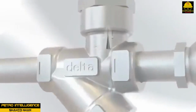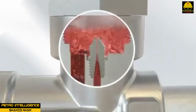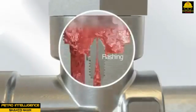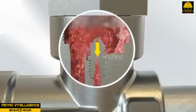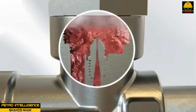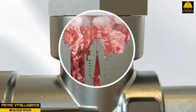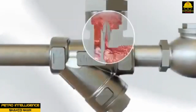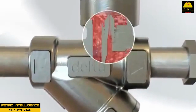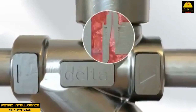All steam traps are designed to distinguish between steam and condensate. To be effective, a trap must stop or trap steam and release condensate. The variety of differences between the physical properties of steam and of condensate has led to a variety of approaches in steam trap design. Some traps, for instance, are designed to distinguish between the density of steam and of condensate. Other traps are designed to distinguish between the temperature of steam and of condensate. Still others recognize pressure differences between steam and condensate.